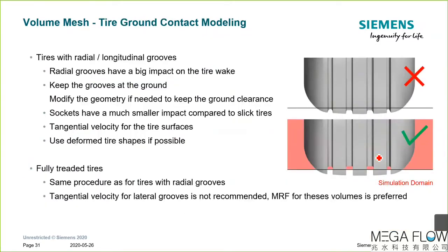So the final slide about tires. Tires are extremely important, as I said at the beginning. The tire wake is traveling downstream. It's impinging on underbody components. So it's really critical. In the past, our customers, and I'm not an exception here, we just intersected the tire with the ground. That's what you can see here, top right. But that's actually wrong, and we are introducing a lot of errors here.